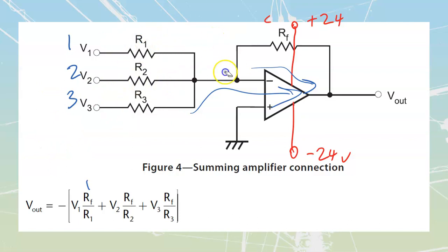The last one that we have is where we take the signals and average them. Once again, really, really handy for doing averaging. We could go back to that same idea of a building, but now all 3 of these temperature sensors are inside of the same loading bay, and I'm going to take an average of it. It's going to be colder closer to the door and warmer closer towards the back wall, but I want to average it. So I need to make sure that each of these is tripled, so they're going to average out.